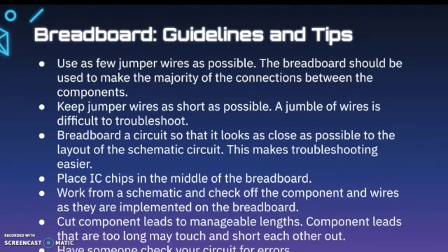When we use a breadboard, it's always good to use as few jumper wires as possible. Inside of Tinkercad, this means thinking about where you're placing things so we have as few wires clicked on as possible. The breadboard should be used to make the majority of the connections between the components, meaning we always want to stagger our pieces so that they're connected inside of the rows and continue to the next row.